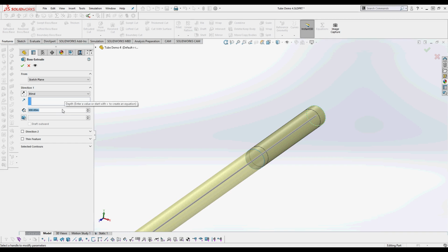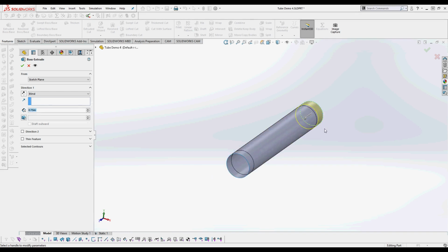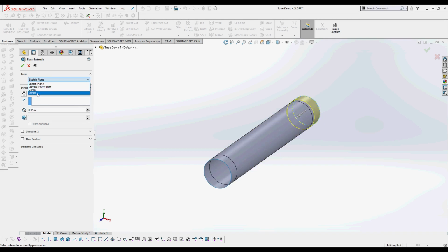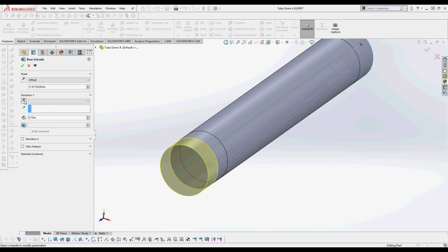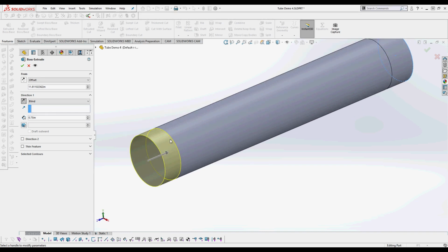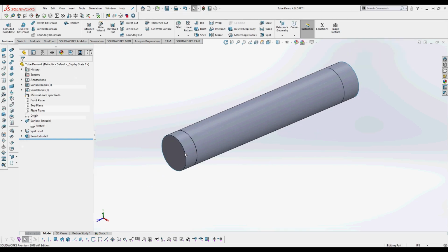We're going to select our sketch, go to the Features menu, and create an extruded boss. We are going to specify that the extruded body is, let's say, 0.75 inches long. And that's just because that's the same distance I used here. And we're going to offset this by the length of the tube. And we're going to set its direction so that it is within the initial surface body that we defined. Okay, so now we've got that. The surface body overlaps with that solid body. That's entirely allowed. There's no issues there in running the simulation.